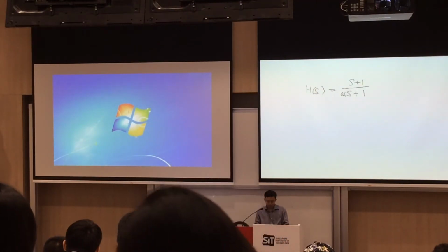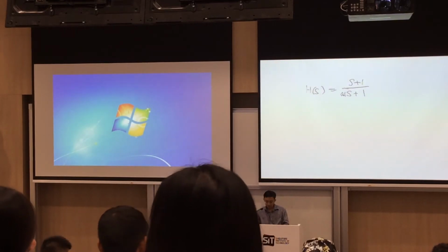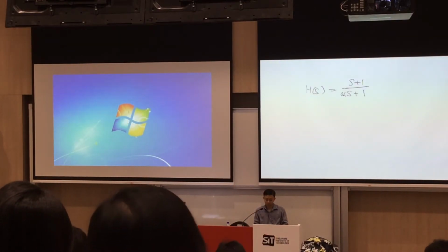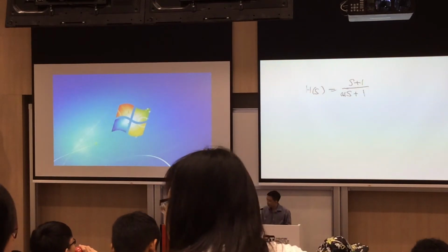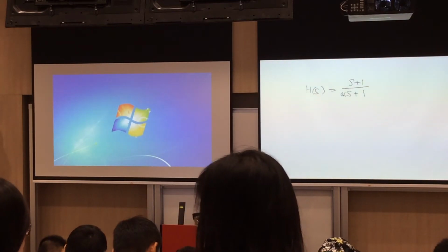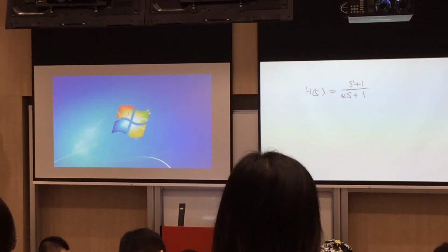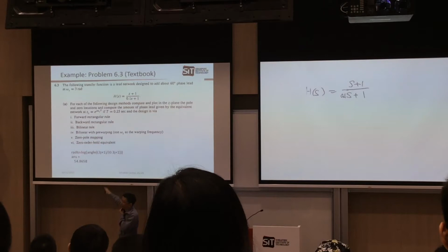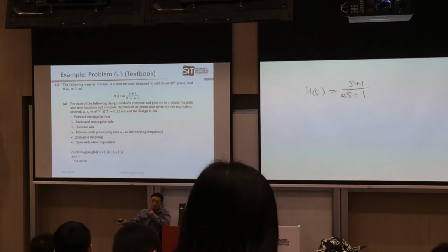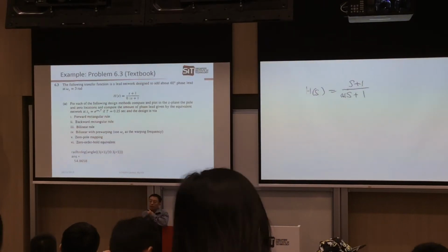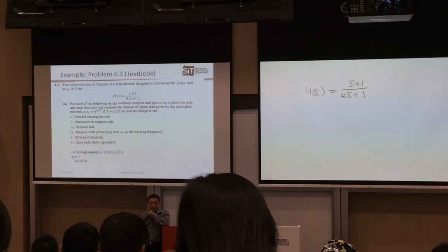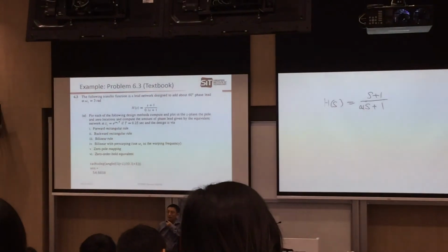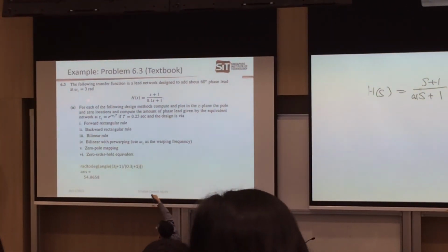So if we use MATLAB, basically, if you run the MATLAB command, you can calculate the phase angle. You can also use a calculator, right? This is a transfer function. Then we are going to do the frequency analysis. If your frequency is 3, how do you use the frequency analysis? You replace your s by j omega, right? Still remember your control lectures? So you replace s with j omega, and now your omega is 3.